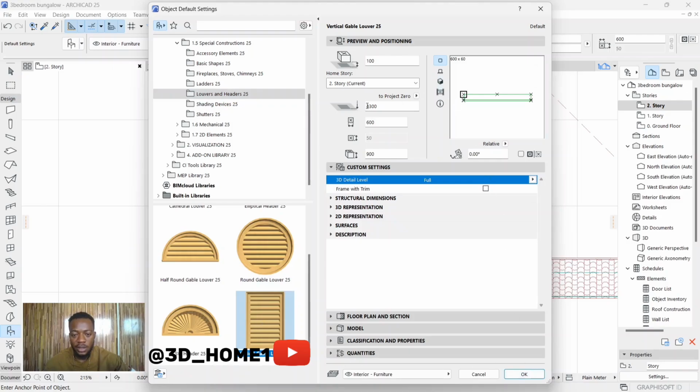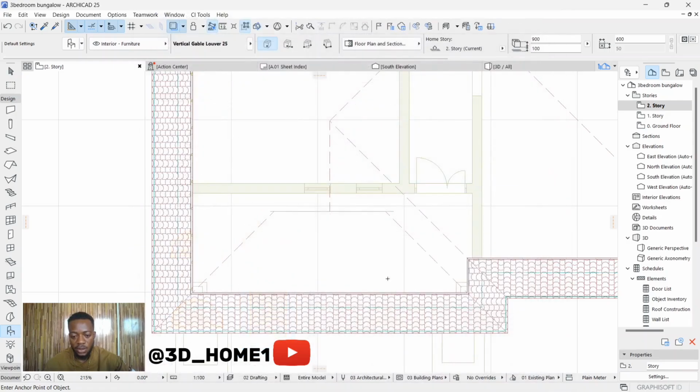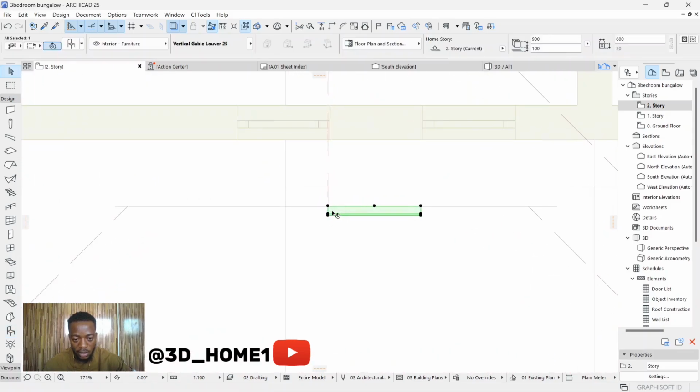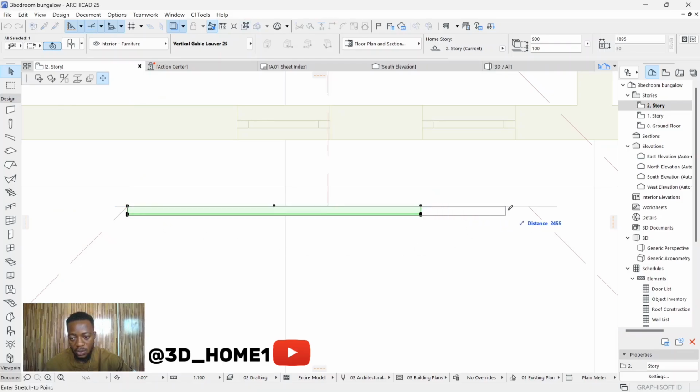And for the height, let's make it 4,300. It's cool. We can stretch it later though if we're not seeing what we want. Now click this one here, and then click here, stretch this point. Look at stretch here, move node, while this one is drag. If you click on drag, it will move everything. So bring this one here, hold down this one, take this one back.